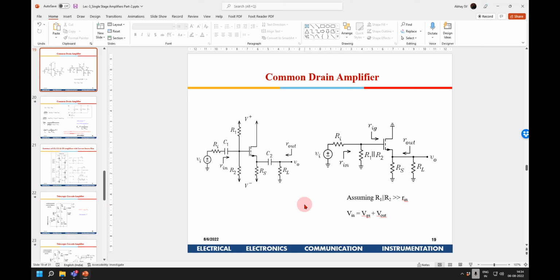I was getting around 1.2 volt there, and here I required around 1.1 volt. So I just put that small change. So that is how we need to think when we are making multiple stages. If you are able to match that DC level, then we can do that.